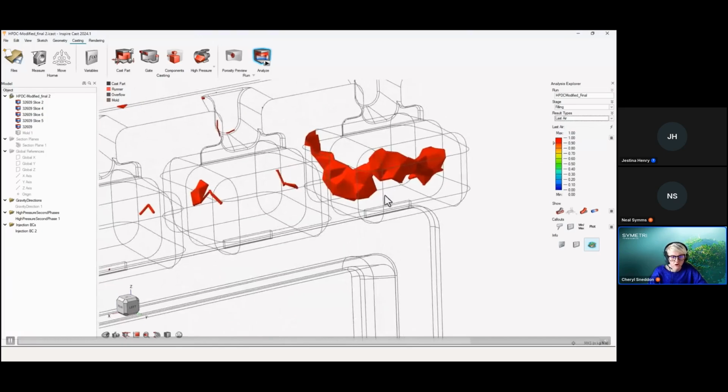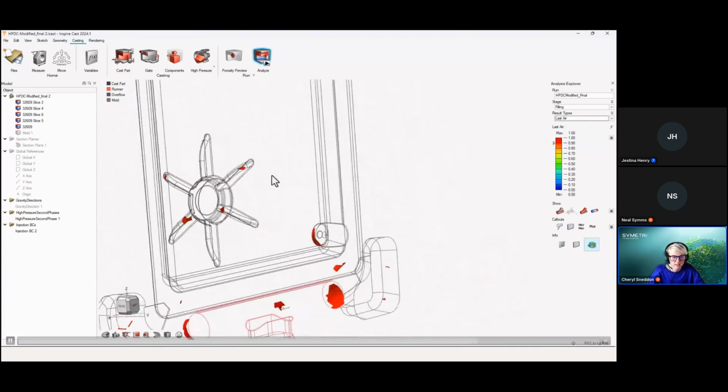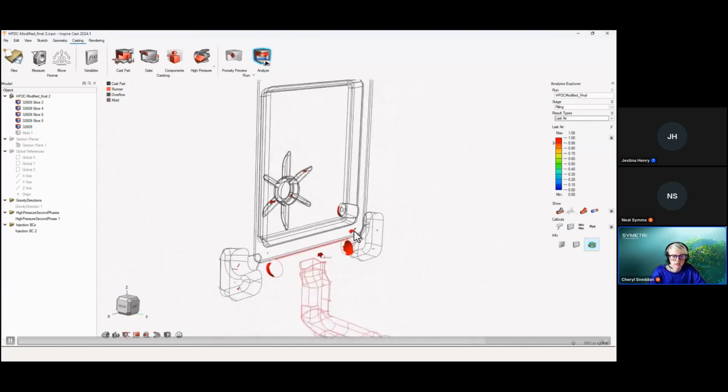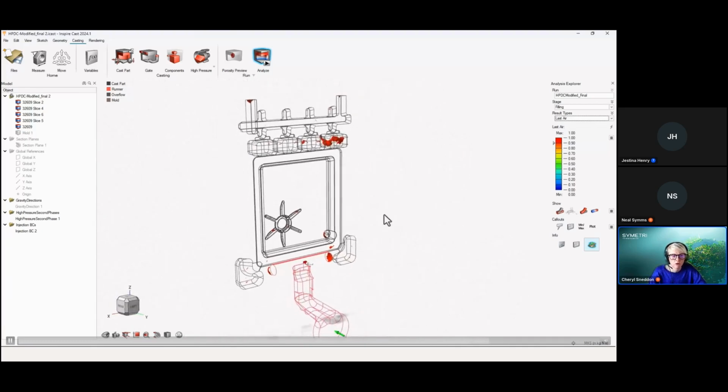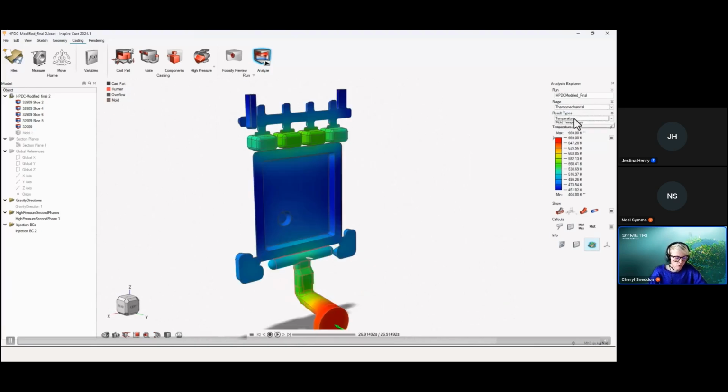So you can see here the red areas are actually physically showing the last air of when the material was pushed through into the die. So we can readjust if there's too much of that in the model. We can readjust the model and also readjust the overflow areas.